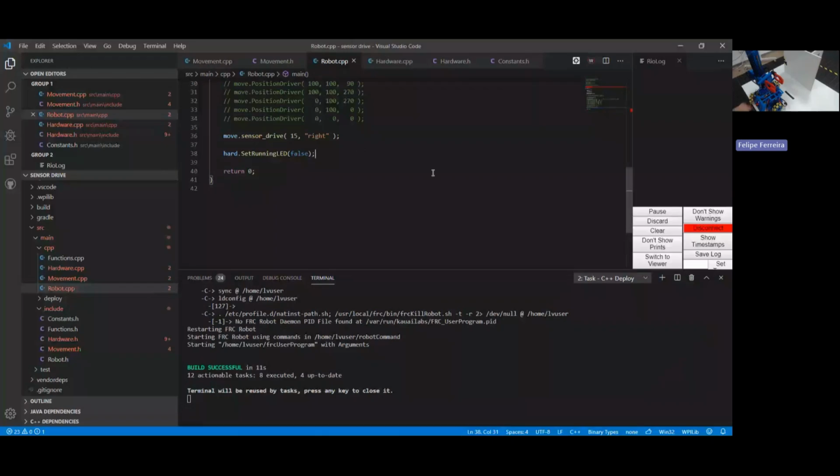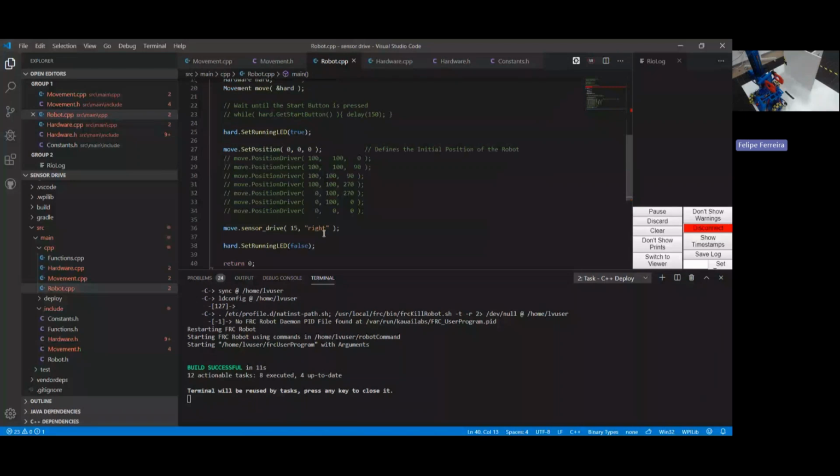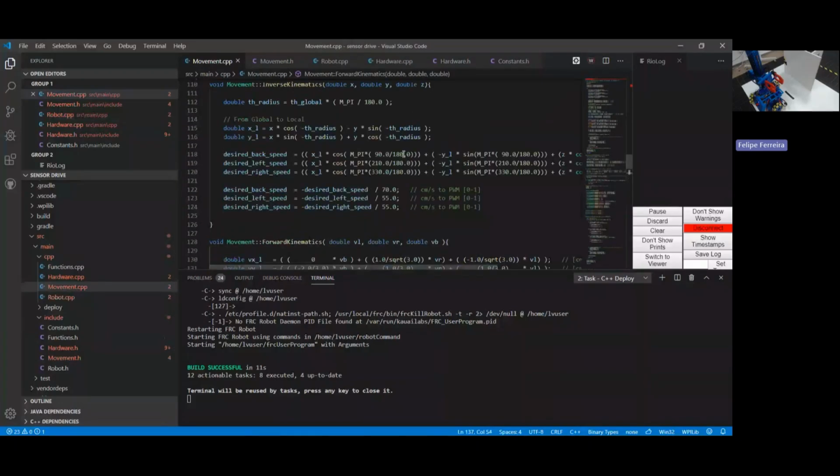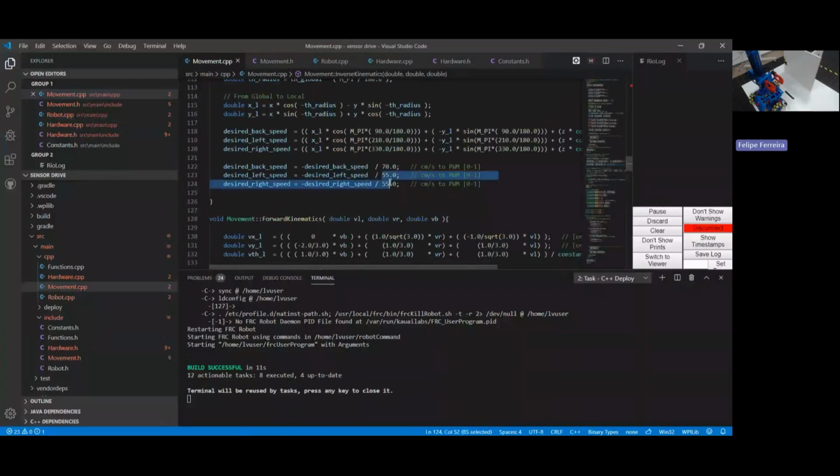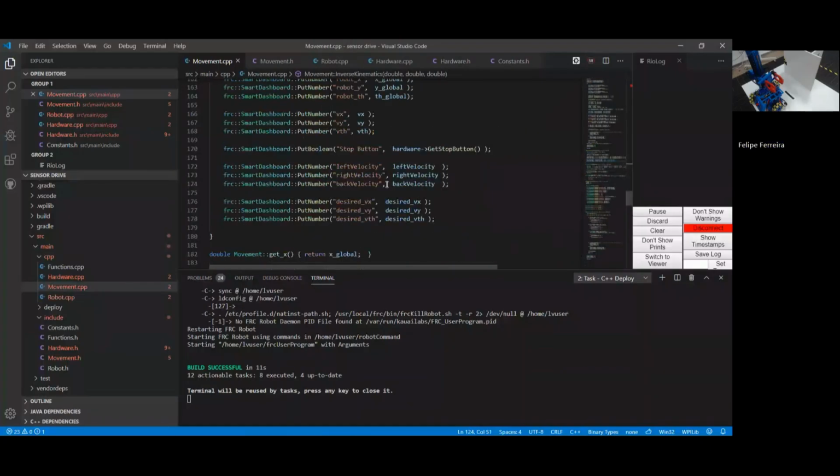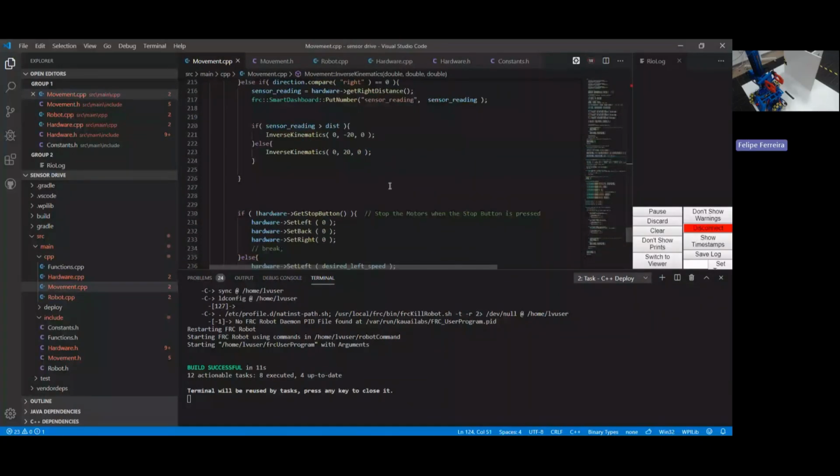This robot is having an issue. I think the problem is with this VMX. The robot from last week didn't have so many issues. But anyways, right side works, left side works, front works. Here, because I don't have PID in this code, I just compensated through the power to balance with the weight of the robot. Okay, and then now you can use it for going right, going left, going front.